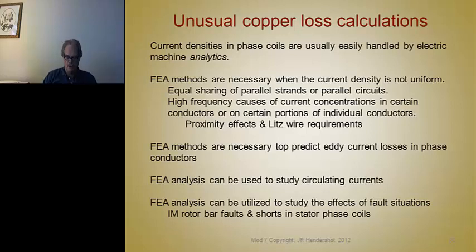Another area that's becoming more and more important, particularly when your solver is connected to an inverter, is that you can use these modern multi-physics simulators to input fault conditions in a motor or an inverter or both, and predict what the results would be. And you certainly need FEA coupling to those multiple physics simulation systems to predict the effects of faults and shorts in all kinds of machines. You can have broken bars in an induction motor, and the FEA simulation of the effects of that can go all the way to predicting how it affects noise and vibration of the machine, besides performance.